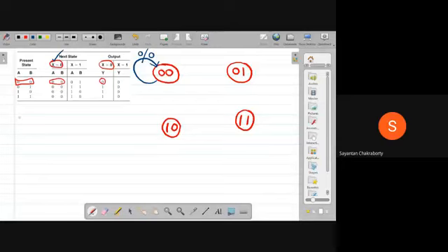So if I mark this input divided by output, note that this input is at time t and output is at time t. So it depicts that if at time t the system is at state 0, 0 and the input is 0, then the corresponding output will be 0 and there will be no state transition taking place. Right?